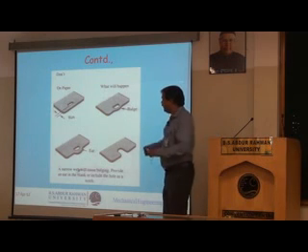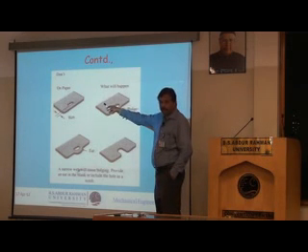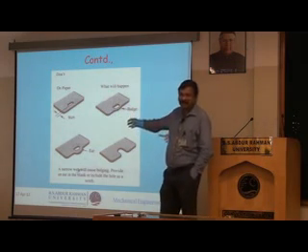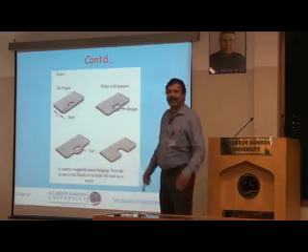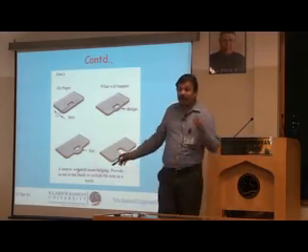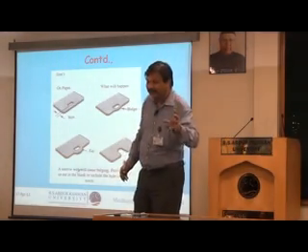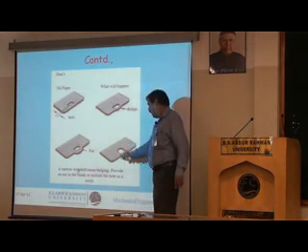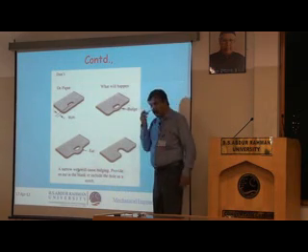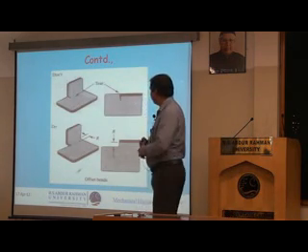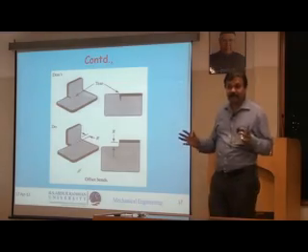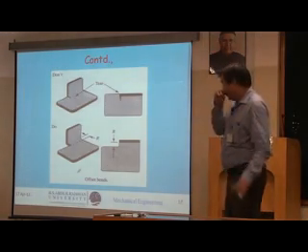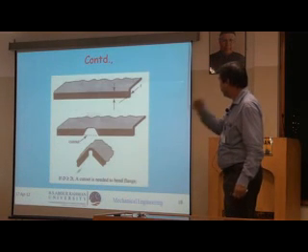If you design a punched hole like this, on paper it may look nice, but when you manufacture, it might bulge here. Are you able to appreciate? When I punch a hole, the material may get bulged here. A designer must foresee these problems, and then either design it like this, or remove the material here and provide it as an opening. Next slide please. So there are many such considerations in design for pressed metal components.